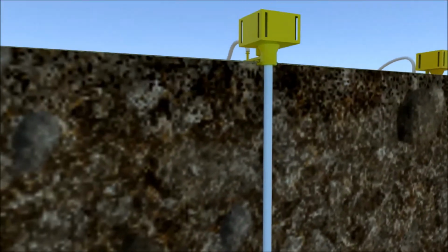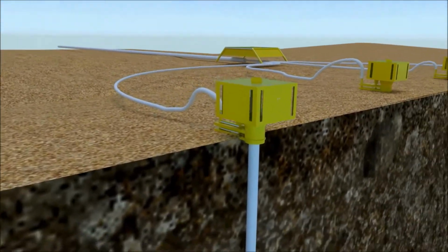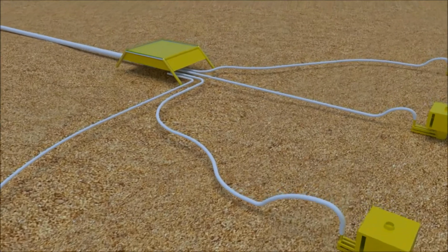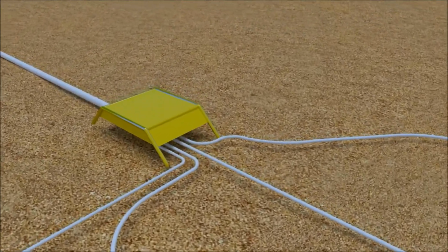In life-of-field simulations, the mass and energy balances for produced fluids through a production network is calculated. The calculations commence at well inflow and terminate at the inlet to processing facilities. The networks are solved subject to user-defined production targets and constraints.